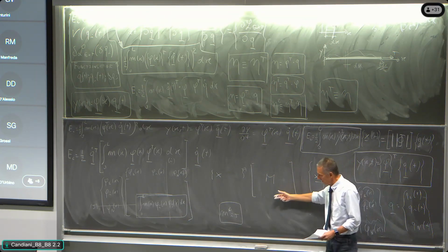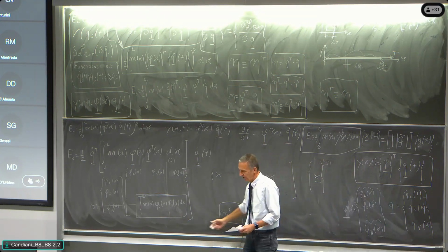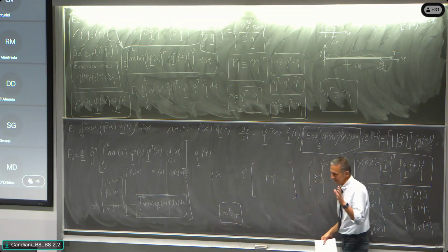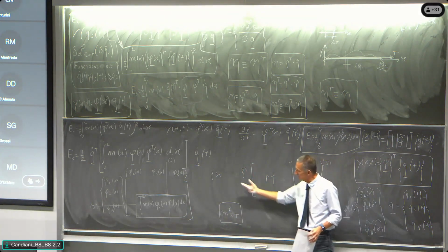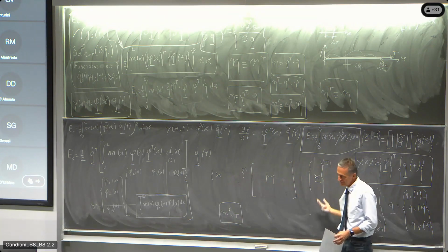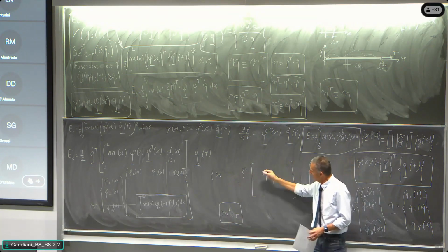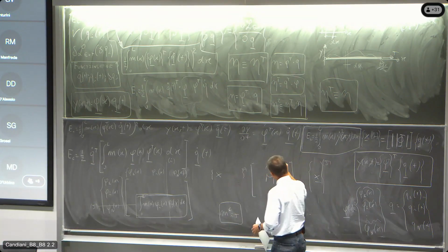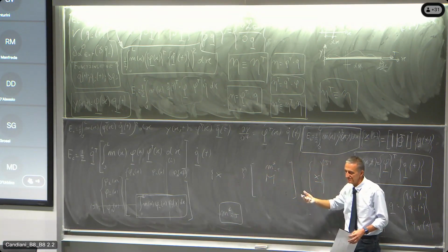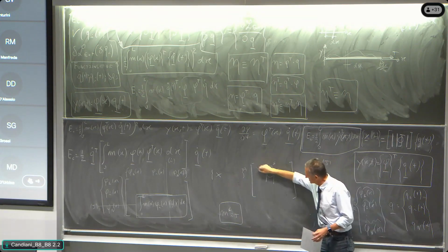What we are doing in the n degree of freedom, we are weighting the distribution of mass through the eigenvector I and the eigenvector j, calculating m star I, j, and discovering that they are all null unless on the diagonal.